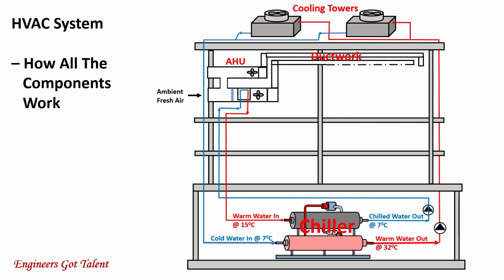The air is filtered by a panel filter and a bag filter. The air is cooled at the cooling coils, and its temperature and humidity are also controlled. The filtered air goes into the ductwork and branches out to different rooms to provide good quality filtered and conditioned air. The low temperature conditioned air picks up the heat from the occupants and equipment inside the rooms. The dirty, unfiltered air is drawn out of the rooms and goes back to the ductwork. From the network of ducts, the air is channeled back to the AHU and is vented outside of the building.